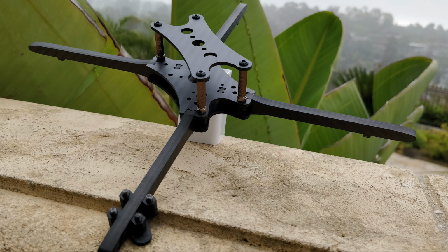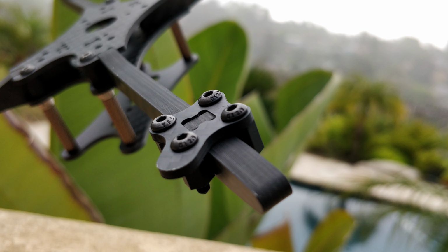There are some box frames that have these cross bracings, like a box around the whole thing, and in my opinion, because I've built and flown them, they do fly differently, but I don't think it's because the box is acting like a wing. I think it's because you have these vertical, flat surfaces that help you direct your thrust and also keep you from sliding sideways.